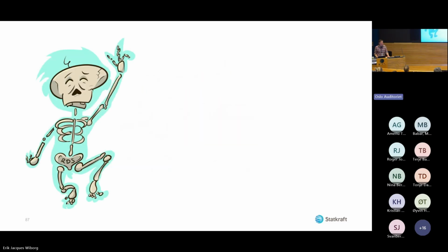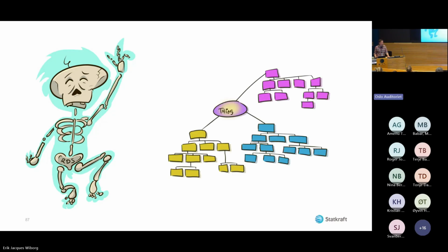The RDS is the skeleton of any information model. It does not flesh it out. It only will label different nodes, and then you need to attach information to those nodes, to those components, those systems. RDS doesn't do that. It just gives you the hierarchical structure. It just gives you the skeleton.